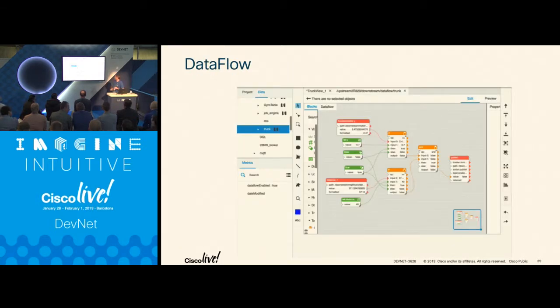Okay? And this is really how a data flow works in this case. So with the value from the accelerometer, we have some reference value here for inclination. We have a distance sensor that gives you the distance from the closest wall. And then we have two if logic blocks. If this, then that, if this, then that. And if those two ifs are true, then I'm doing something. In this case, I'm publishing an event on MQTT. And by publishing the event on MQTT, it goes back to the truck and turns on the flashing lights.